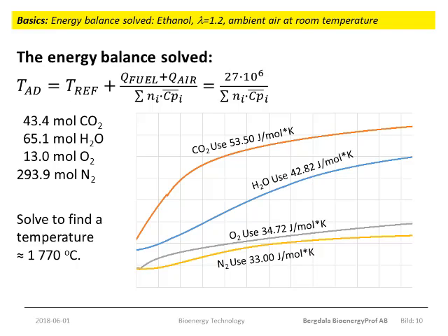When you do this type of estimate based on the adiabatic temperature, you must always have a margin. In this case, the margin is 370 degrees, so it is okay to say that ethanol may be used in this application.